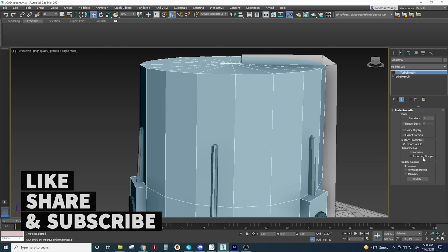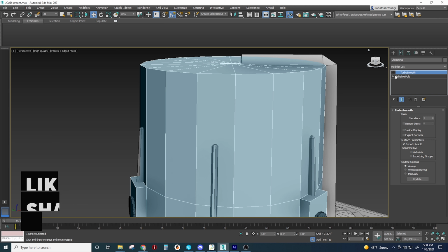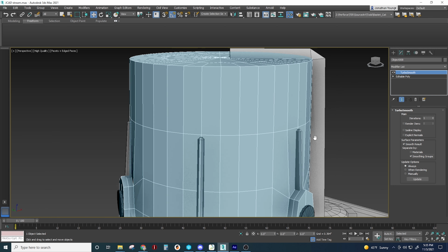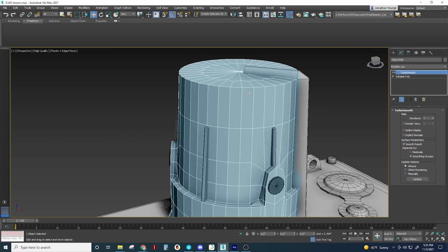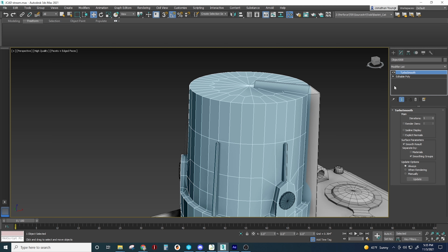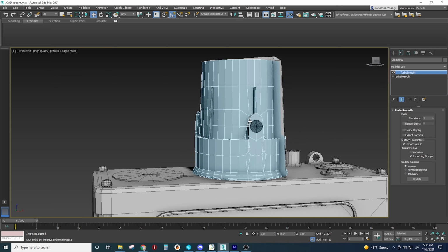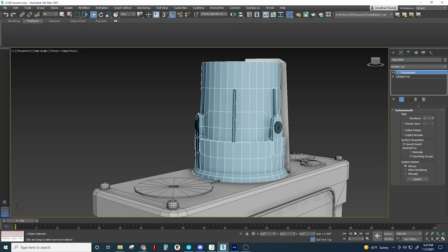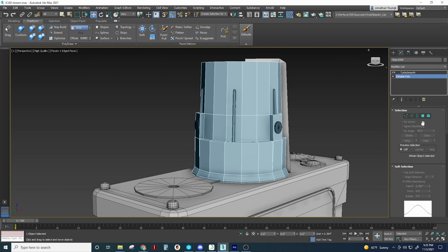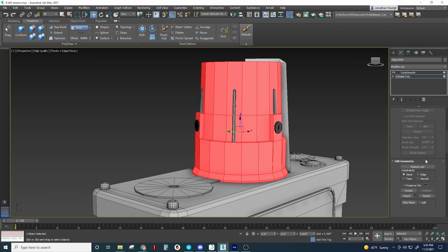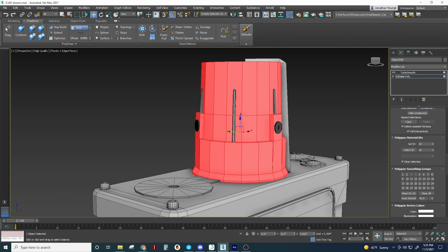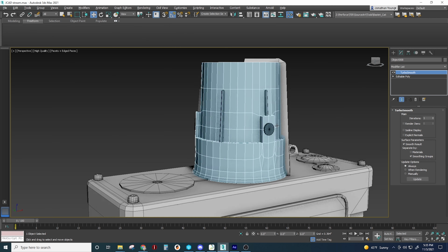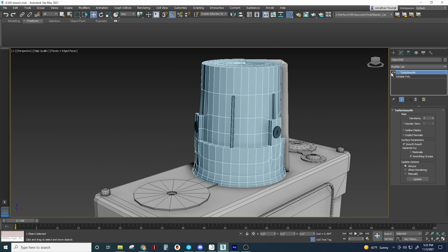A quick way I like doing this is I'll separate my smoothing by smoothing groups. Sometimes it's set up well. You can see that these different smoothing groups, it does not smooth across them. But other times it's not set up correctly, so I can come in and do a clear all, I can do an auto smooth, and let's see if that is closer. It's a little closer.